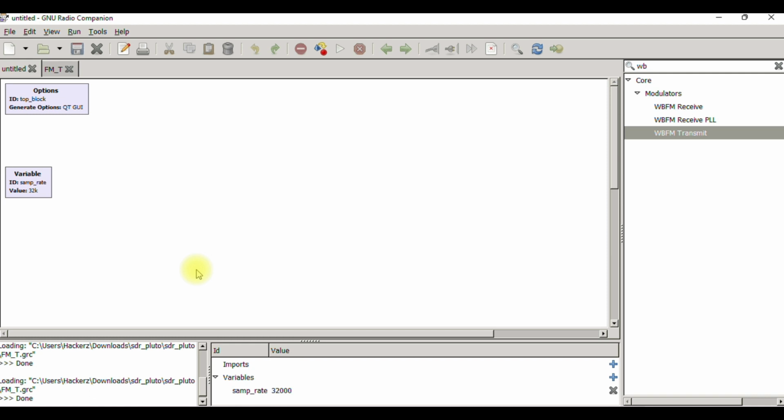Or else, the second option is to connect one more SDR module to a next system where we implement an FM receiver block, and we connect a speaker to the computer and start the simulation. Then the receiver SDR, with its local oscillator tuned to the same 90 megahertz as the transmitter SDR, receives the signal. It is processed in the computer itself, and we can hear the output signal in the speaker of the computer.